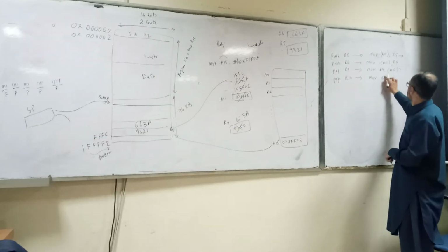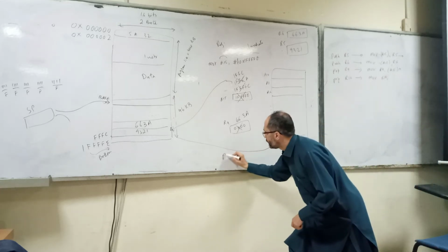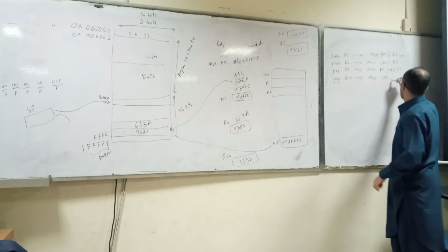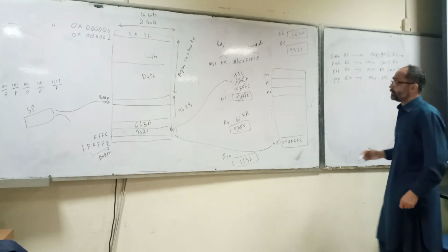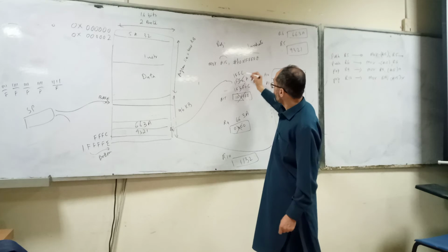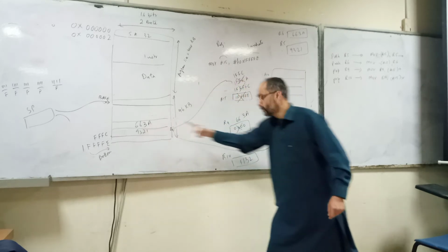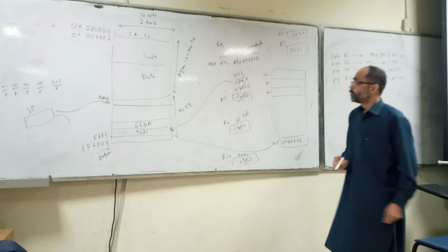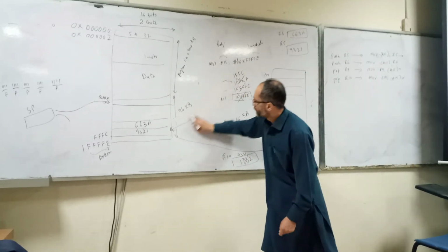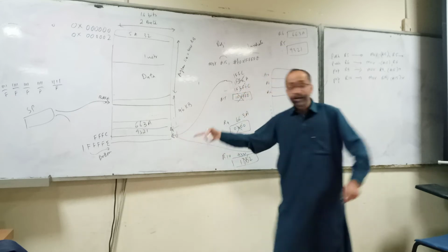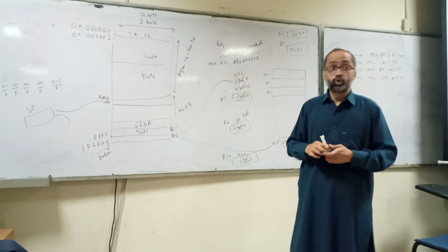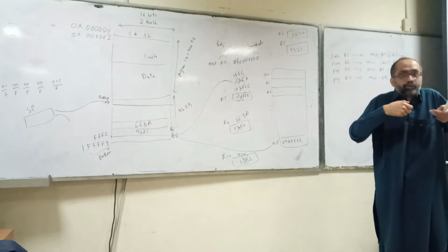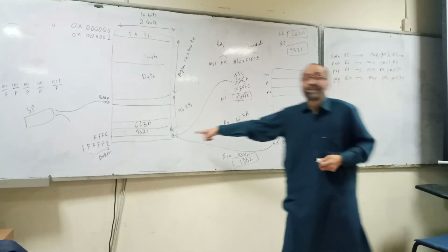Okay, now if we say pop, move R10, sorry. Let's assume that the initial value of R10 is 1132. So move R10, A15 plus. So actually now the stack pointer is pointing to this location. This value will move into the register R10. What is now the new value? 9321, and it will again point to this location. So now we have two things. If you want to again pop some element from the stack, now the stack is empty.